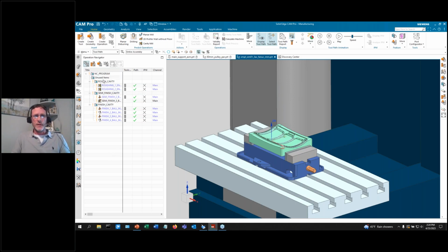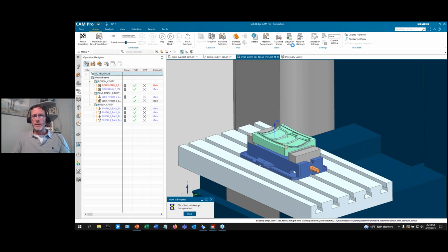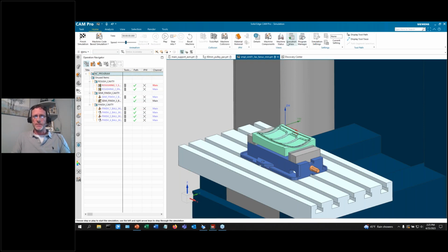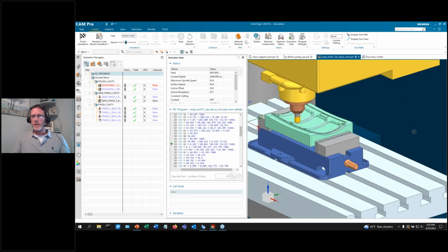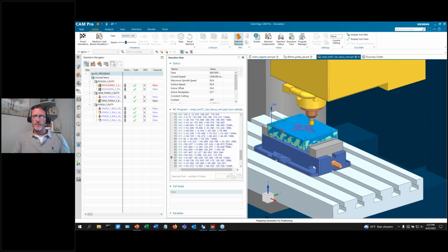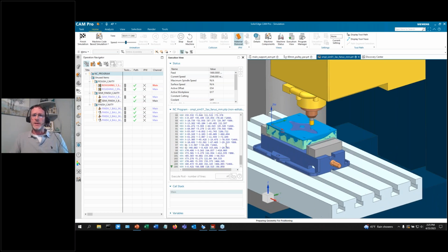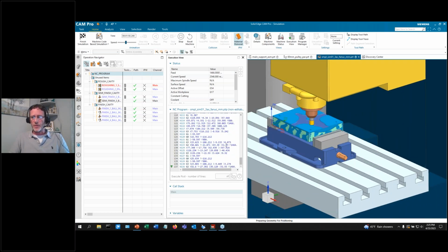And then when you get finished and you program, we do a simulate machine. Now, simulation is based upon the G-code, run through a CSE driver that is built for your specific machine tool. So now we have our execution view. This is the specific G-code that's running. And we can play, and we see our full kinematic values with material removal. So this is the highest tier of solution set and capability that you can have with the CamPro solution.